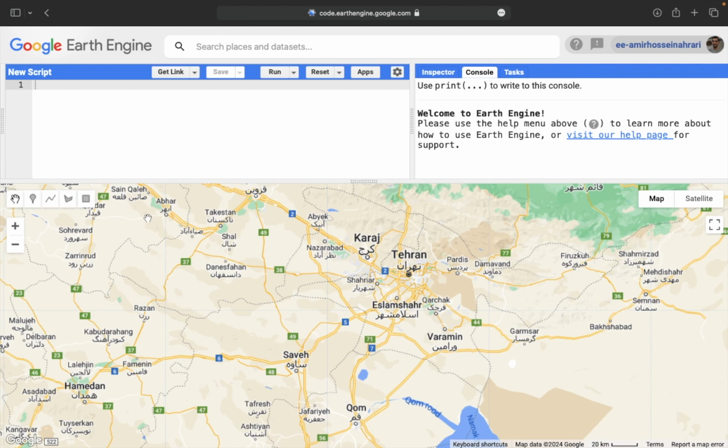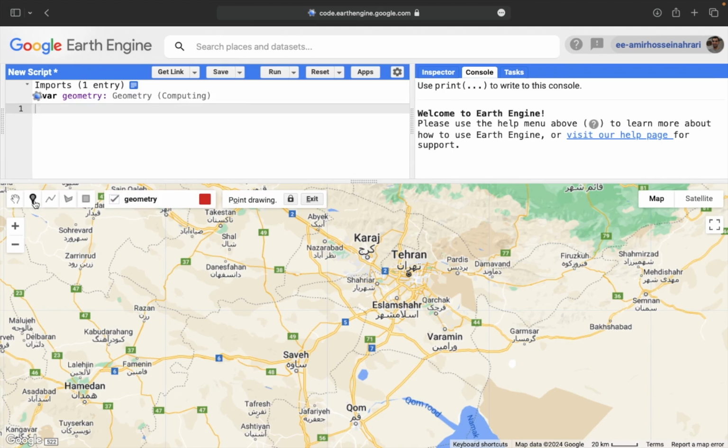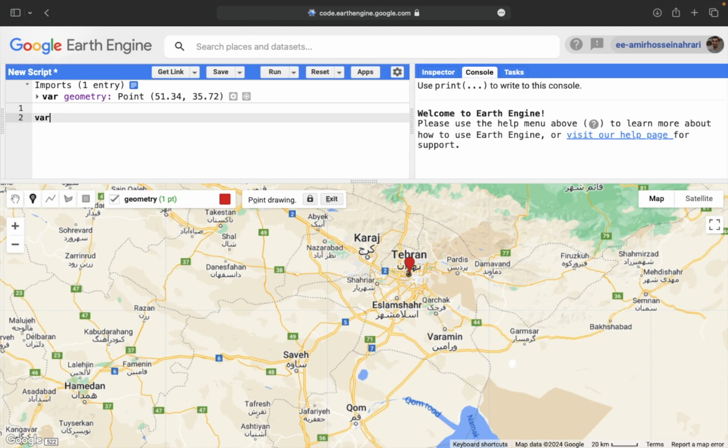So it's very simple through the FAO product to select the region of interest and then do further processing based on the available shapefiles in the Earth Engine data catalog. So first select your region of interest by point-based geometry. I just pin my region of interest with the available drawing tools here, and then make a new variable equal to, for example, the urban or target area, or simpler, ROI, region of interest, equals